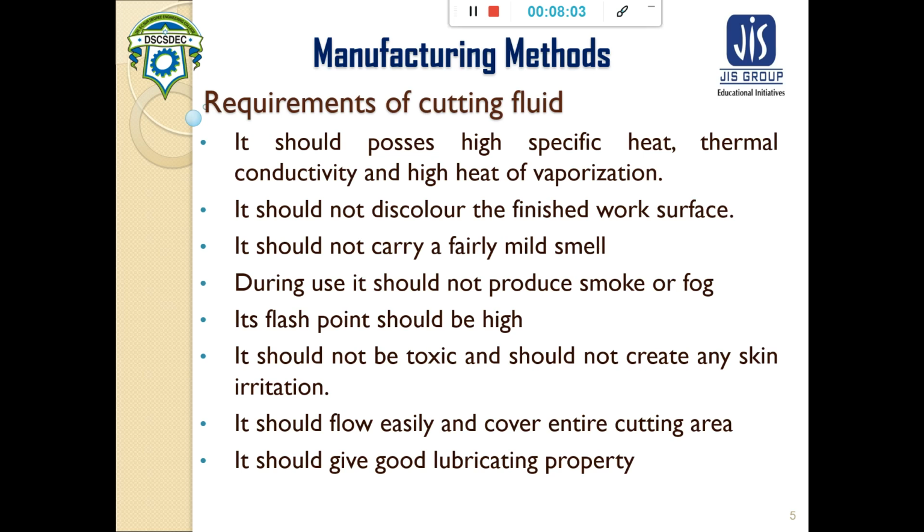Secondly, thermal conductivity should be there. If there is no thermal conductivity, what will happen? At the chip tool interface, the temperature will always rise, because the coolant will absorb the heat but will not transfer it anywhere.